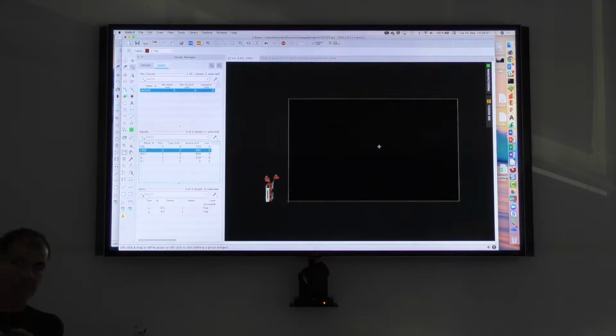And depending on how I build the board, I can have different ways of drilling into the board. If I have 2 of them, I can drill there. I can connect the top layer with the first inner layer. And I take the other one, I can drill from the bottom layer to the second inner layer, and I can put this together, and I can drill through the whole stack again.